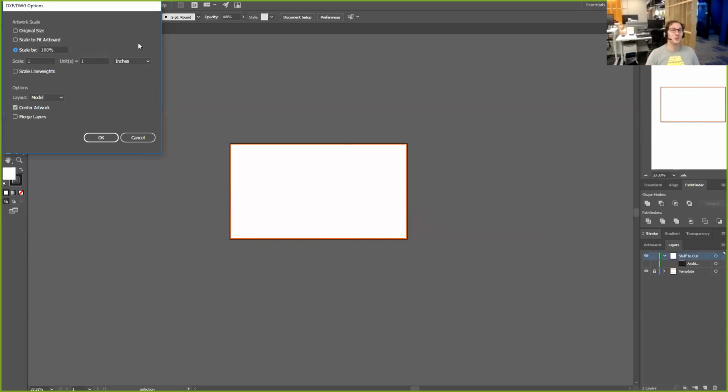And so if you want to import your DXF, let's get the units right. I am going to choose millimeters, and then I'm going to fix this. I'm going to say 1 unit in my file that I'm importing is equal to 1 millimeter. Right? Perfect. And I'm going to scale this 100%, meaning I'm not going to scale it. Right? It's going to come in 1-to-1, or net size, or 100% size, whatever you want to call it.